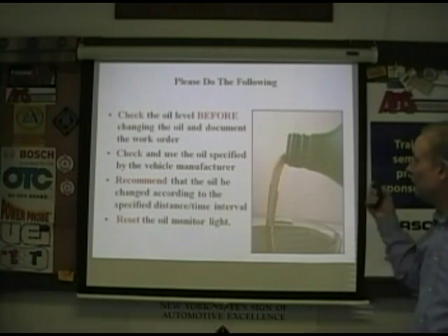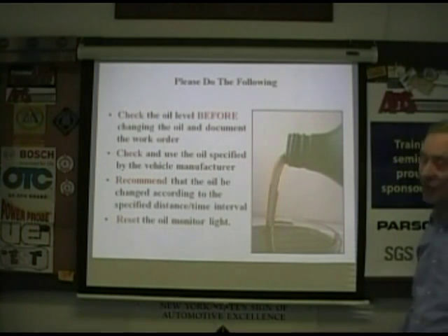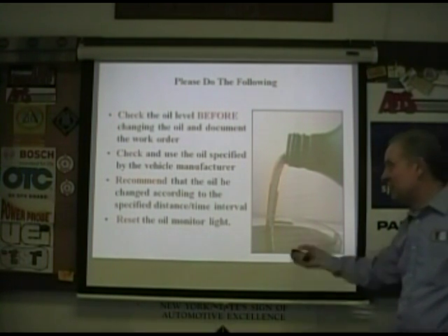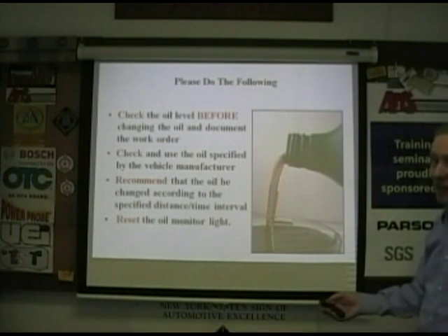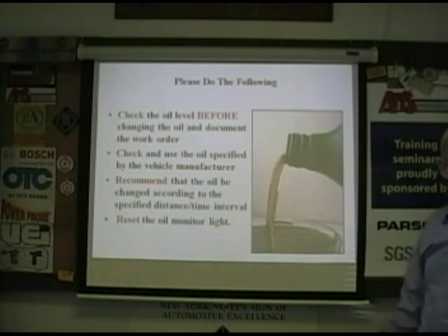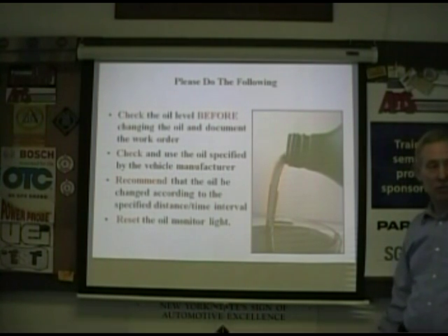All right, do the following. Check the oil level before you change it. Know where you're at, how much it's using. Document it. Check that the oil you're using meets the manufacturer's spec. Read the can. Is there a place, if you have a problem, you could have your oil tested?